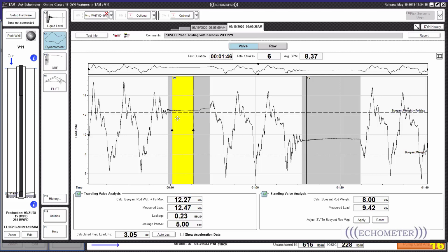You want the power transmission from surface to bottom to actually be used for lifting fluids, without so much friction in the system, or so many over-dimensioned components that can lead to a very low system efficiency. So as high as you can, but usually over 50% would be okay for a rod pump system.